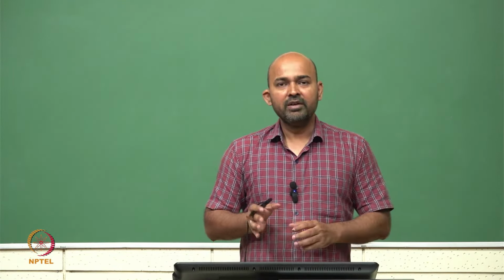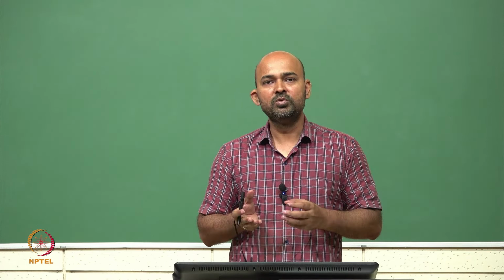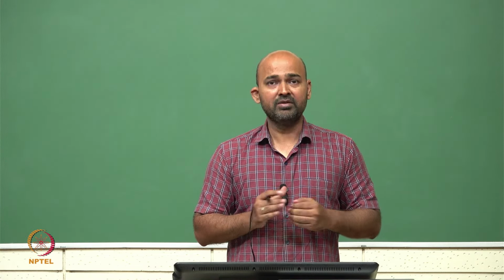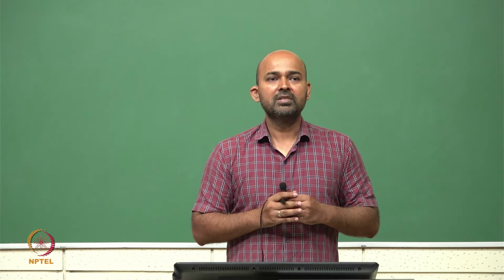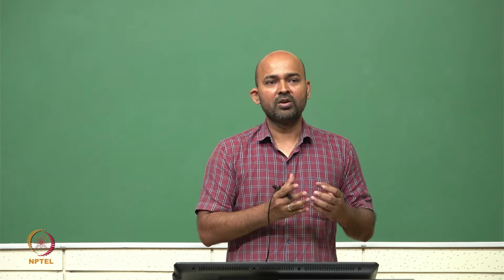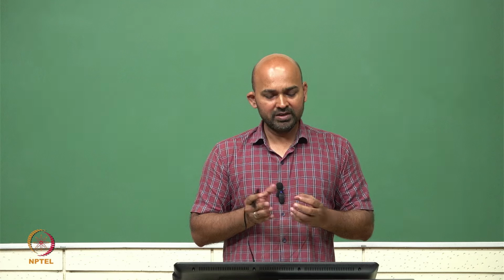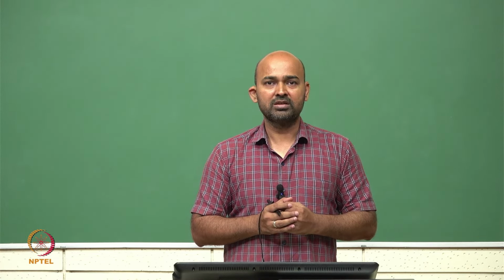So, today we discussed the MOSFET, which is mostly used as a switch in all our ICs and discrete components as an active device, and the BJT. There are some circuits which require the use of a BJT and cannot do the same function with a MOSFET. So, only in very limited cases do we use BJT structures in our electronic system design.